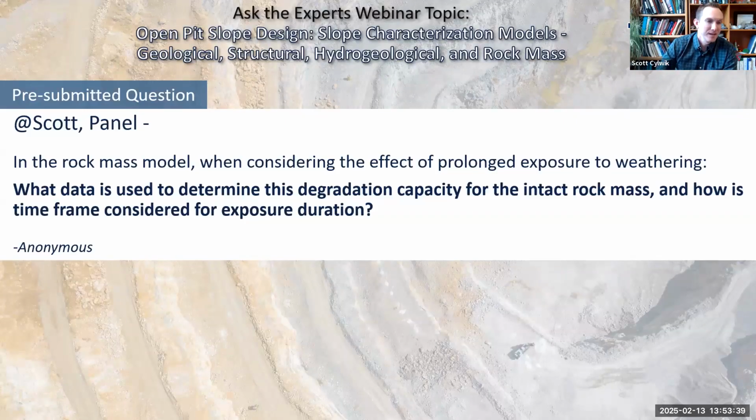Others have an extreme change when exposed to the acid, and that would just depend probably on the mineralogy that's seen in that rock. We've also done the exact same thing in the field for some slopes where we have testing from 10, 15 years ago. It's a slope that's below a heap leach pad, drill a new hole, do new testing on the borehole, and compare that to the data from 10 to 15 years ago, and see if there's any change.